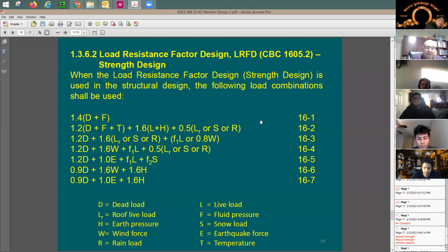Live load is going to be the loads that you may change. Furniture, I can move the furniture easily. I know some people would say, but furniture, I mean, look at this table here. I didn't move it for years, but I still call it live load. So the problem is when you have dead load and live load, and both of them give you, let's say, moment, or axial load on a column or shear or whatever, right? Can I just add them to each other? I mean, can I just take the dead load and live load?